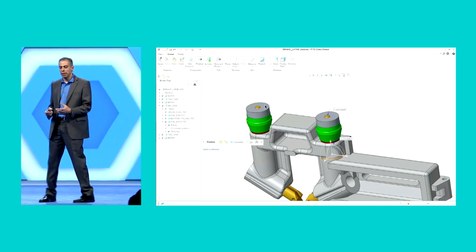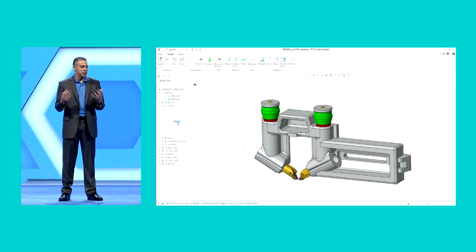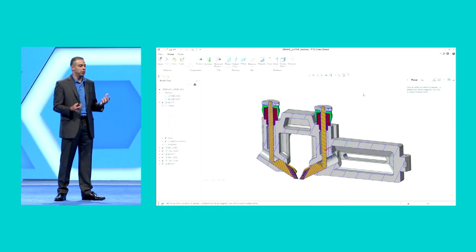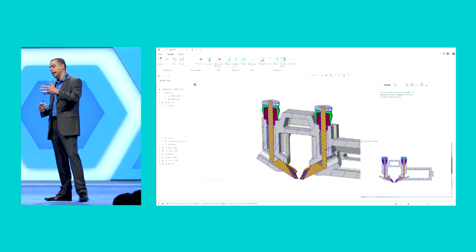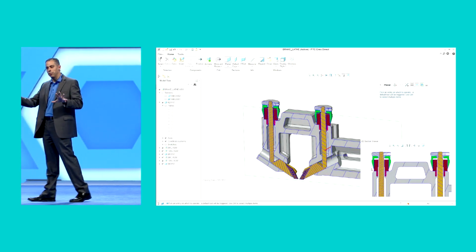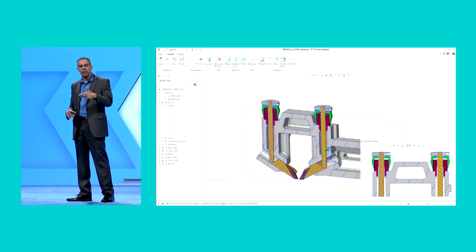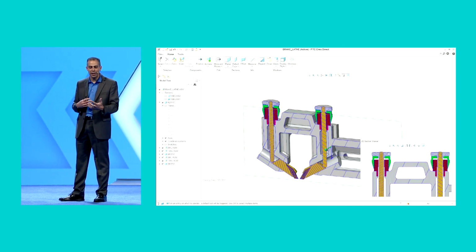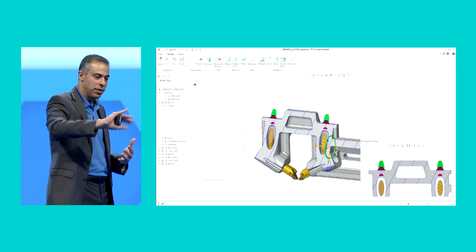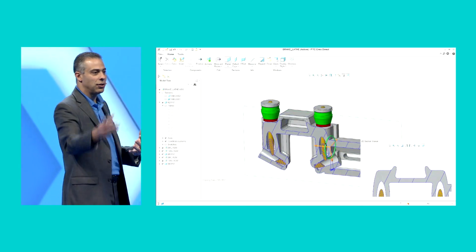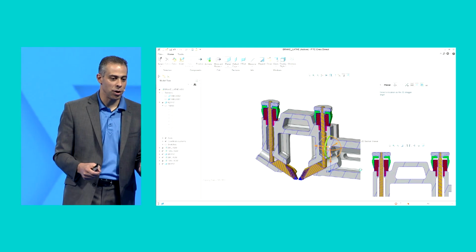So that's shared occurrence. I'm going to show a little bit more about cross-section mode in Creo Direct. It's pretty interesting. There was quite a bit of investment there. It's as simple as picking a plane. You see this cross-section mode, but we've got other capabilities as well. We can do things like see the cross-section in a 2D window. We can see interferences dynamically. You see that bright red area. That's an interference in the cross-section. You see that dynamically as you drag. That dynamic interference can be shown whether you're linearly dragging or dragging rotationally. You can change the angle of the cross-section right there in the window. It's all dynamic, updating in 2D and in 3D for you.